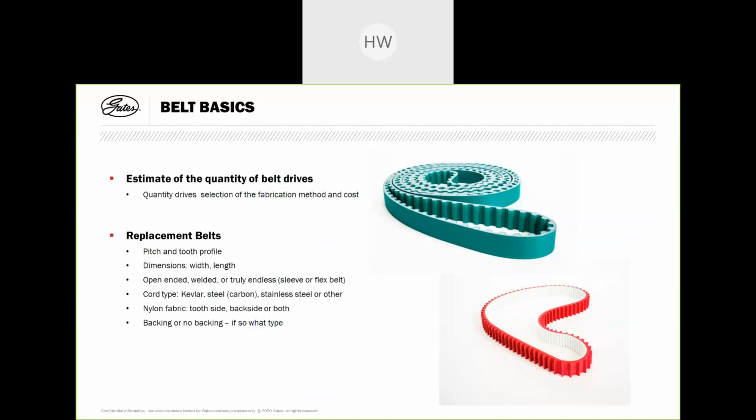And then, of course, especially when you have an existing drive, we need to know the pitch and tooth profiles, the dimensions. If it's an open-ended, an endless welded or truly endless belt, we need to know the core type, if it's aramid or stainless steel, if you need nylon fabric or if you have any other fabrication on it, backing profiles, and so on and so forth.